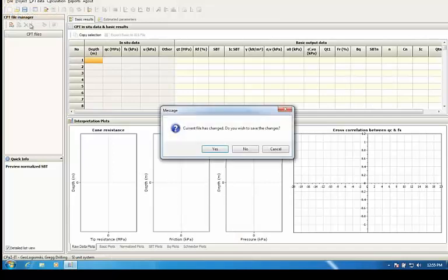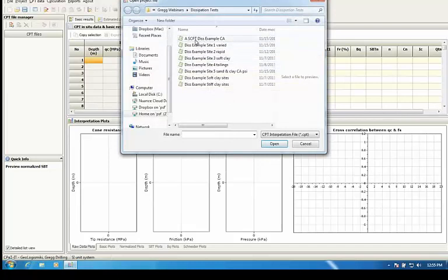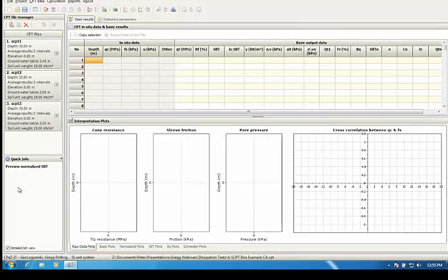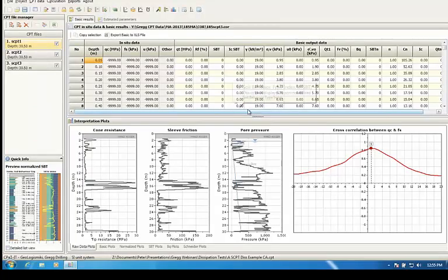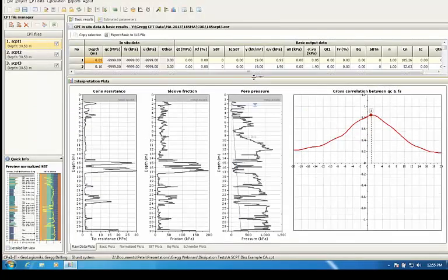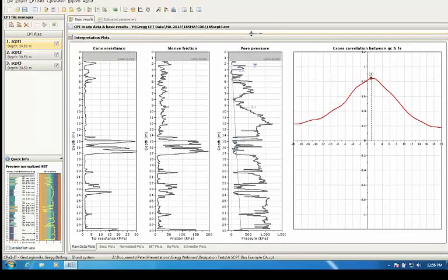Most of the time, people are just guessing. They do a pile load test maybe a week after driving the pile. It's a somewhat arbitrary number. It obviously should depend exactly on the type of soil. So that concludes the main part. So we've got time for questions.